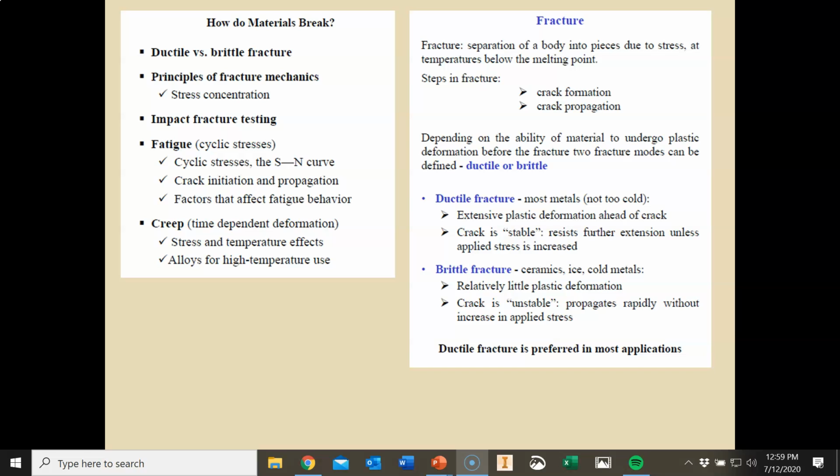Ductile fracture is a type of fracture characterized by extensive plastic deformation or necking. This usually occurs prior to the actual fracture. The term ductile rupture refers to the failure of highly ductile materials. In such cases, materials pull apart instead of cracking. In ductile fracture, there is absorption of massive amounts of energy and slow propagation before the fracture actually occurs.